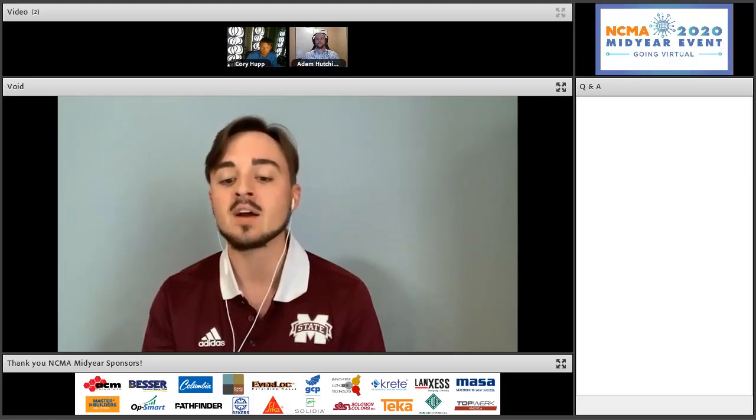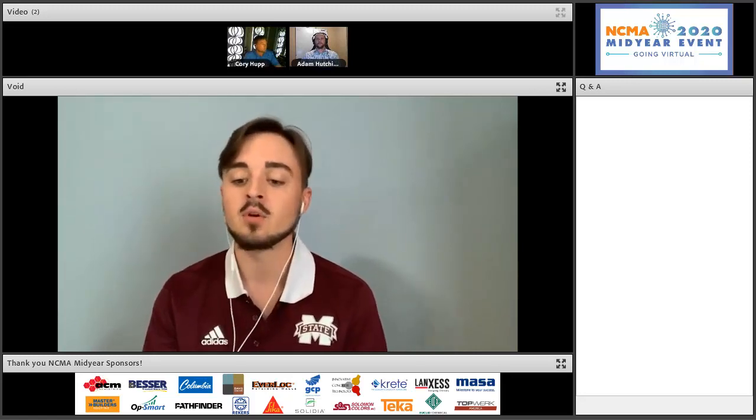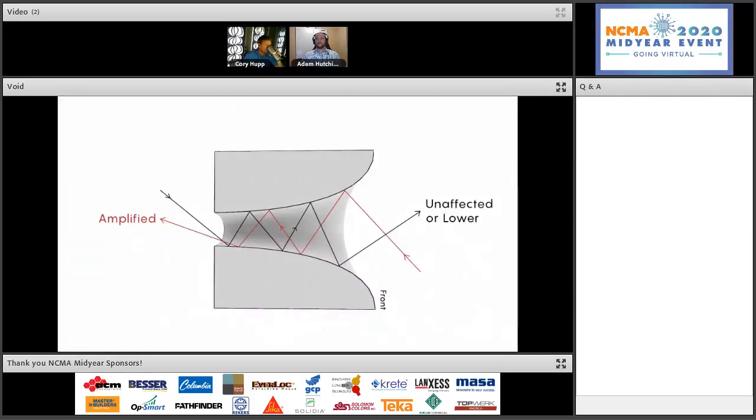Throughout the design process, we continually noticed the possibility of an acoustic effect through the horn-shaped hull of the concrete unit. To better understand what capabilities our design had, we reached out to a local acoustic engineer, David Woolworth. Initially, we believed that the shape of the hull would act as a high-pass filter that would allow mostly high-range frequencies to pass through by funneling them through the hole, and simultaneously we thought that this would make the low-range frequencies blocked or really diminished in effect on the other side of the wall.